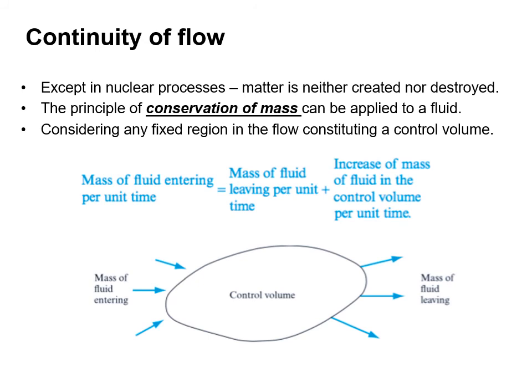With the exception being nuclear processes, matter is neither created nor destroyed. The principle of conservation of mass can be applied to a fluid, considering any fixed region in the flow constituting a control volume. So the mass of fluid entering per unit time must equal the mass of fluid leaving per unit time plus an increase of mass of fluid in the control volume per unit time.